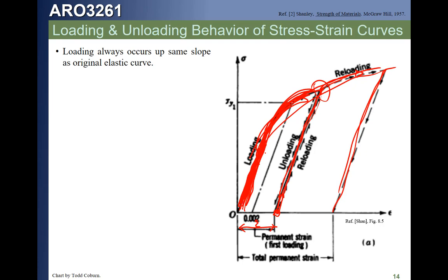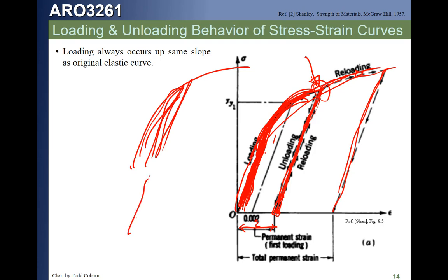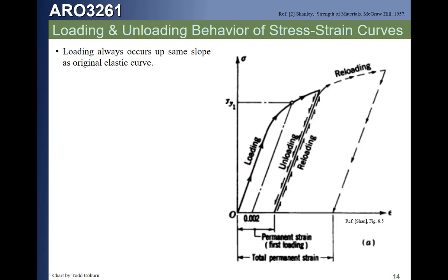While this material that's loaded down in here didn't actually yield until we get past the proportional limit, you'll notice the yield of this new material, once we've loaded a little bit, has climbed from whatever it was up to this new value shown right there. So if you load up a structure in the lower load realm, but above the proportional limit, you're going to end up changing your stress strain curve until it looks a lot more pronounced, where that's your new FTY. So if we went to the original curve, we would take this slope, move it to the 0.2% offset, but under low loads, eventually that 0.2% offset will become the point where your yield is. So even though we kind of winged it and came up with this 0.2% strain idea, it actually works pretty good, because if you load up your structure with any significant load, that will often become the yield after a while. Make sense?